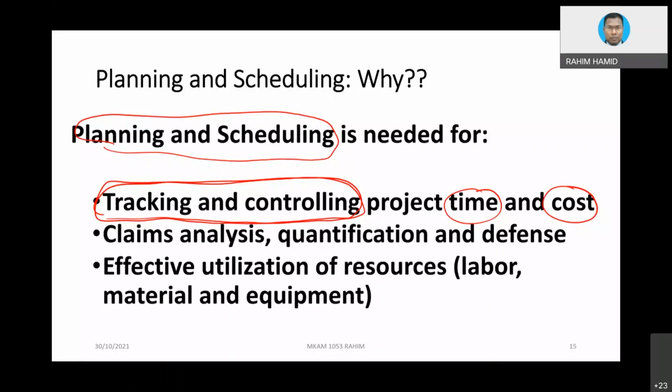Well, that 10% consists of what? You need to provide evidence. You need to provide progress photos, for instance. You need to provide your updated bar chart, for instance, or an updated network diagram, so that people can see it in graphic form.